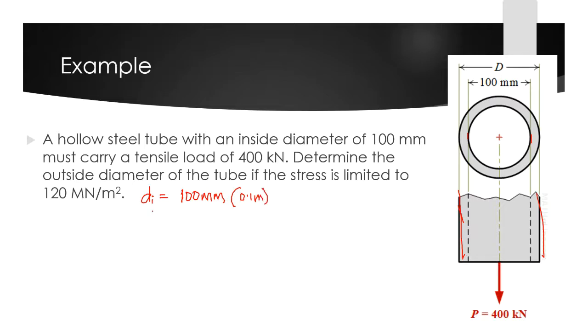And we also have the tensile load or the force, which is 400 times 10 raised to 3 Newton. And the stress is limited to 120 times 10 raised to 6 Pascal. Okay, so we are looking for the outside diameter, or we are looking for the D, the bigger D.